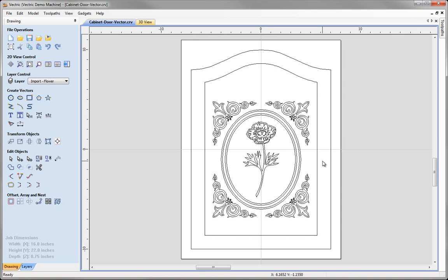Then we again use the snap grid to help us accurately sketch an ellipse. We offset that ellipse inwards to create the rings in the middle of the part. Then we imported a piece of vector clip art, grouped that together, rotated it, positioned it in the corner and made mirrored copies of it. And then finally imported our flower design and then just scaled that to fit and then moved all our data down 1 inch, again making use of the snap grid function. In the companion tutorial to this, we're going to take this data and create toolpaths on it. That concludes this example.